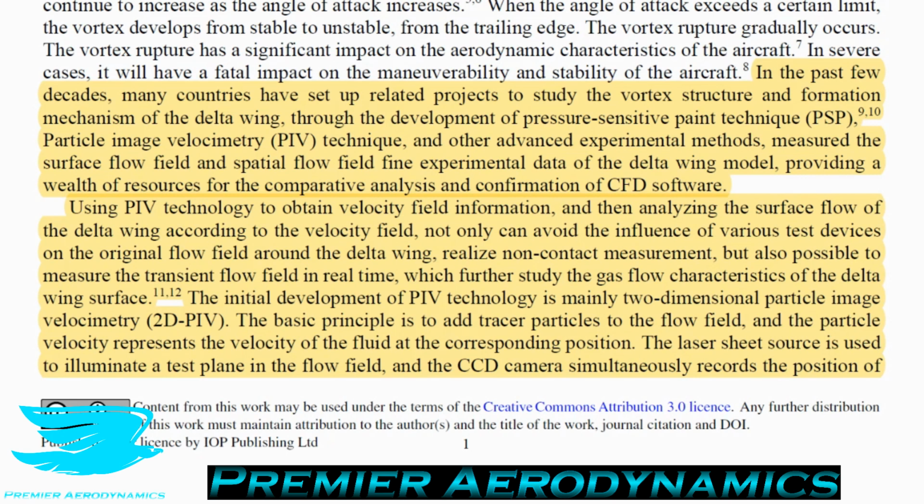For example, boundary layers. If you don't do a hot wire properly, it can dramatically affect a boundary layer, and it will really corrupt your results. So they do have different types of hot wires to get around that. But again, it's far better just to use something which doesn't affect the boundary layer at all, and that's something called non-intrusive. Something like pressure-sensitive paint and PIV, in theory, should be non-intrusive. Pressure-sensitive paint, if you don't do it right, can affect the surface roughness, which then does affect the flow. So you can kind of think of that as intrusive because it does affect the flow.